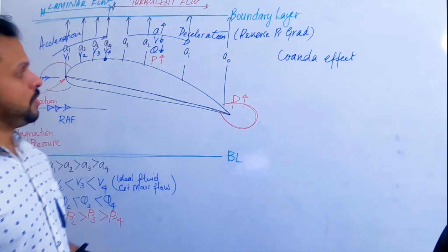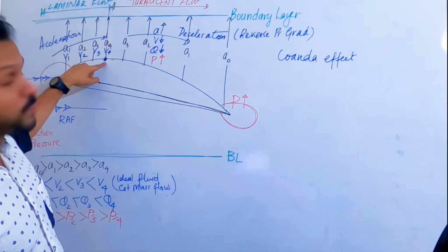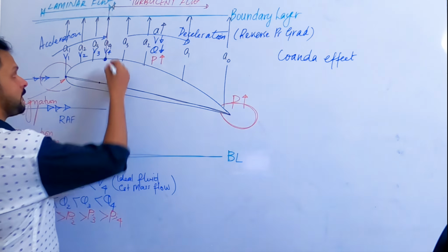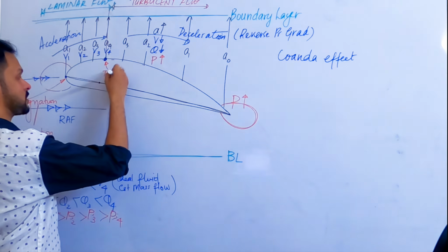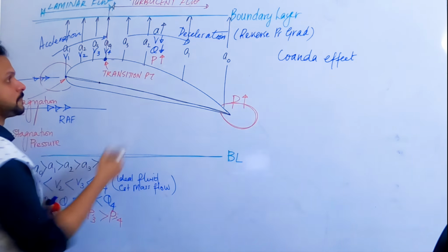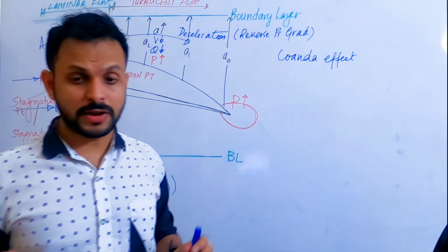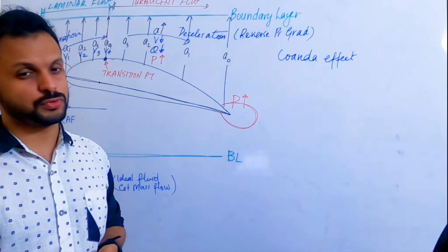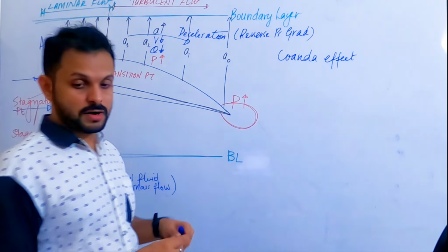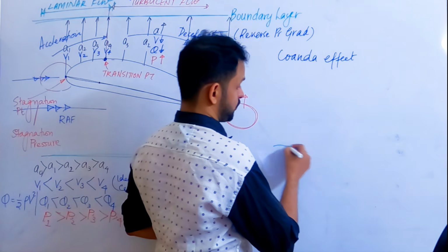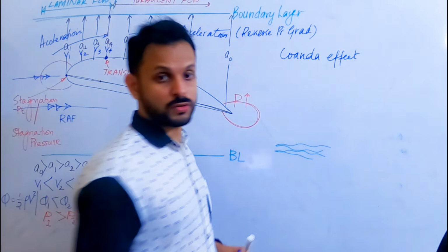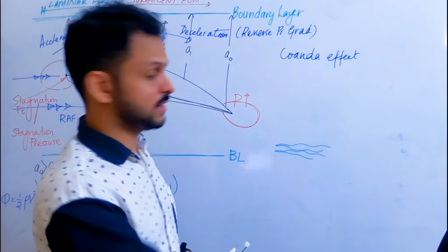Alright, so this point where the flow transitions from laminar to turbulent, what's the point called? Transition. This is what is called the transition point. Is that clear? The transition point is where the flow changes from streamlined, which is laminar, to turbulent flow, which is more like a flow that is crisscrossing. So it's not very linear, as you said, and the layers also cross each other. There is more influence of viscosity and such.